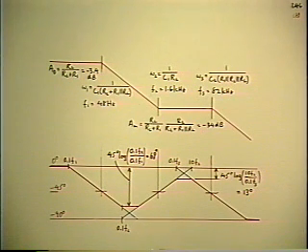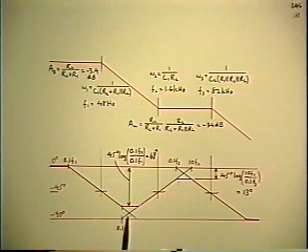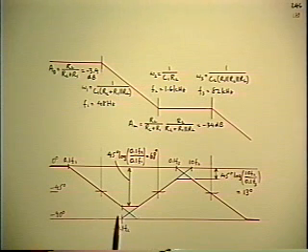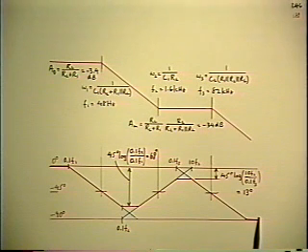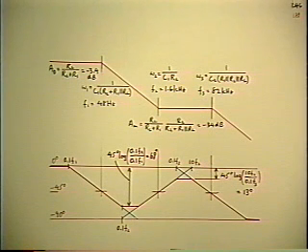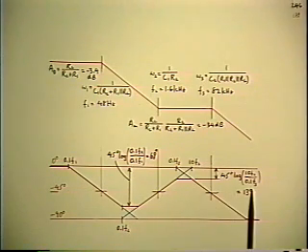Change the values to achieve that. Now, again, subject to the limitations of homework problems, you have to constrain it more than that. So I tell them, change only R2. Because R2 determines one of these corner frequencies, so I can change the overlap. They have to do something else as well, because the phase angle is always going to go to minus 90 at infinite frequency with this circuit, regardless of what you change. So in order to bring that back from 90, you actually have to add another element. You have to put another resistor in series with the second capacitor. And all that does is duplicate the problem.